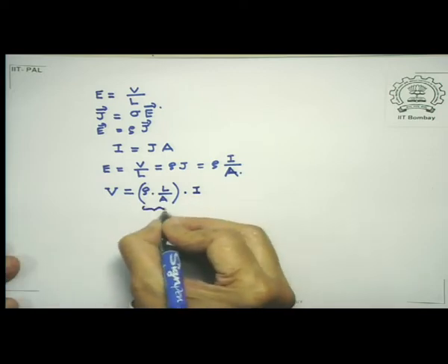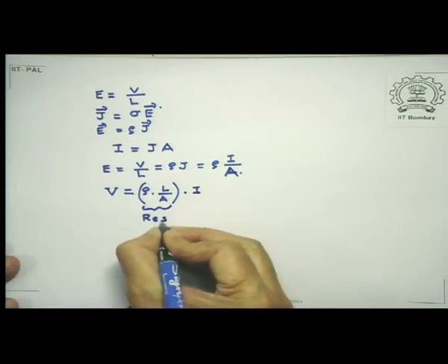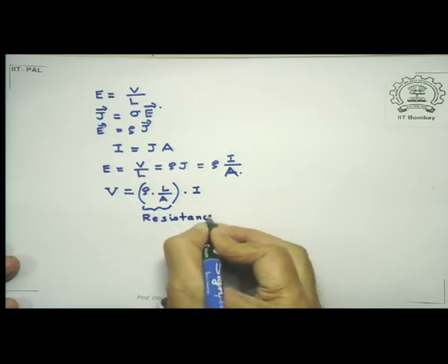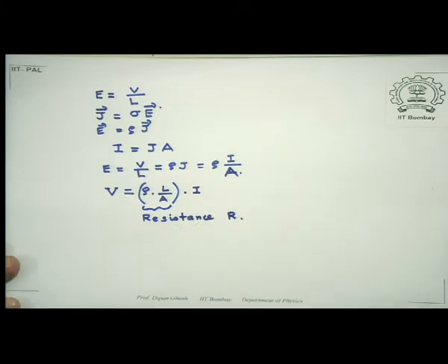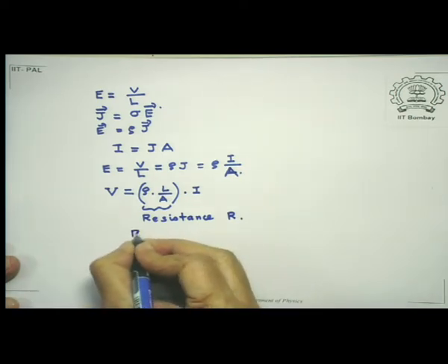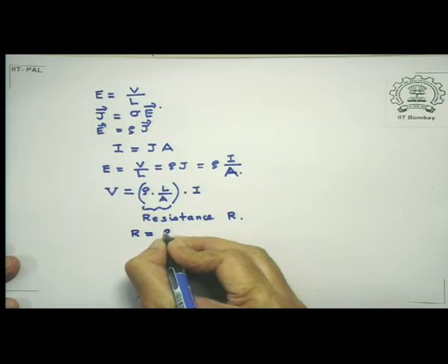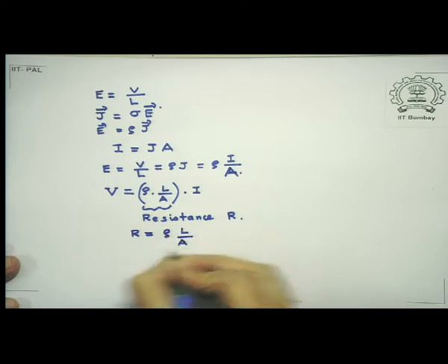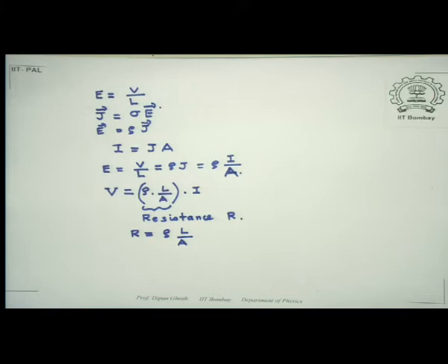Now this is the quantity which we call the resistance and is usually denoted by R. So I find that R is equal to rho L over A, that is, the resistance of a sample is proportional to the length of the sample and inversely proportional to the cross section. Now an ideal source of EMF provides a constant potential difference or constant voltage across its terminals. Now this is irrespective of how much current flows there.